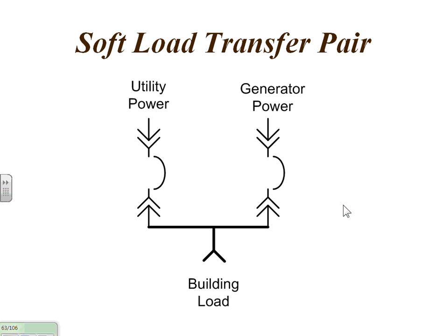They can't be operating at the same time, and the reason for that is, let's take a power outage again, or an exercise period. All generator sets are going to be exercised from time to time. We've got no power failure. Both sources are available, right? We start the generator set. In that instance, we've got a normal situation. Utility is on, so this breaker is closed. We're supplying load to the building.